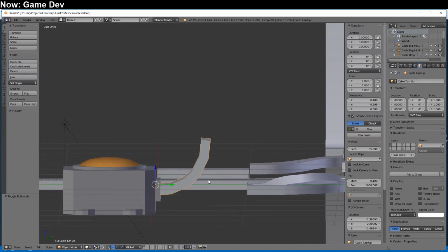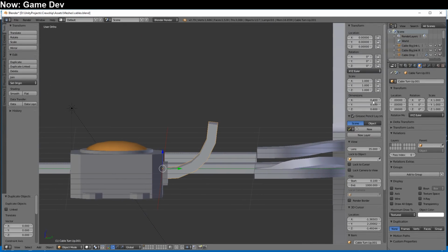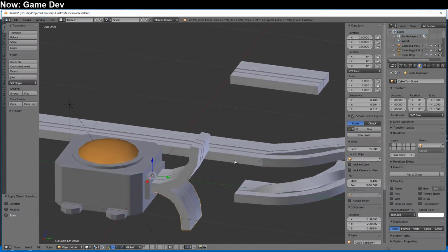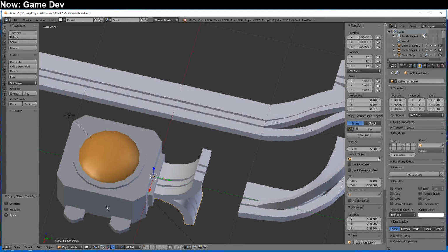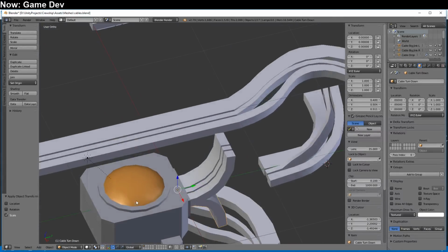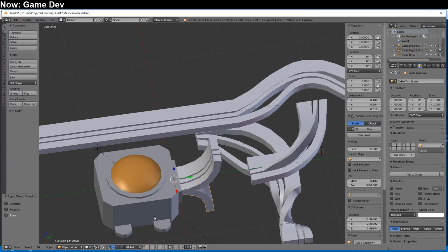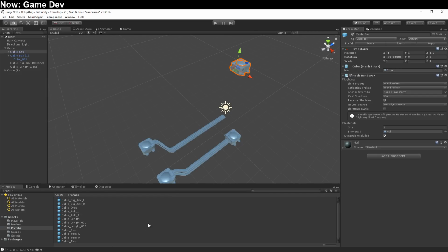Hooray. So that's our turn up, and then we're turning down too, so we're going to go ahead and name it cable turn down. And we're just going to scale Z -1 that, and then apply the scale. And that's going to be our turn down. Fast and easy. The magic of Blender bevels. I really, really wish there was a Blender subdivide on a specific axis command. But there's not, and I didn't want to add a whole bunch of extra crap to it, so...